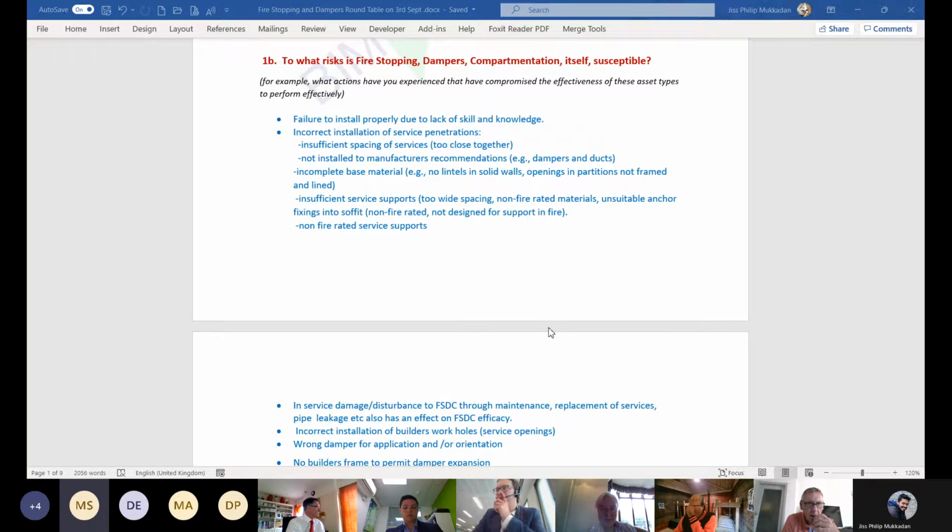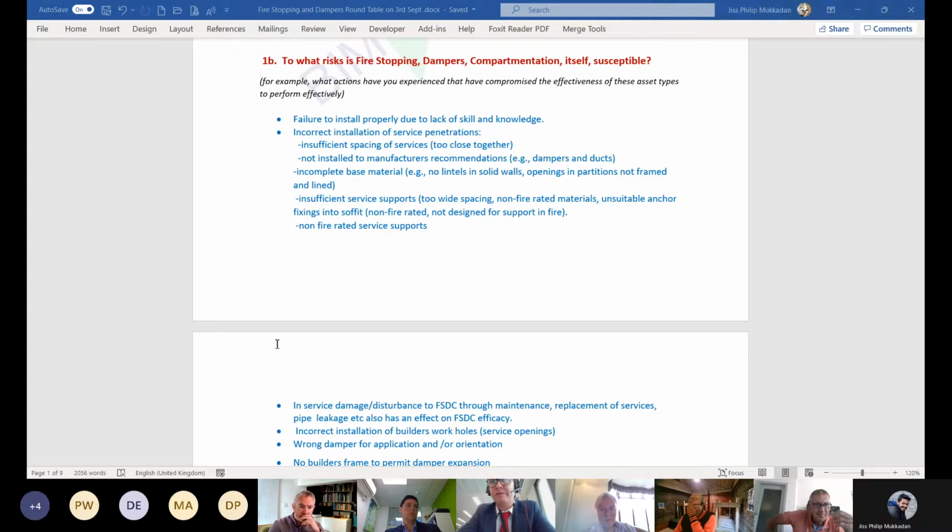I'm not trying to be too over the top. I had to look at 25mm holes for a long time as well. But honestly, the big thing here for me is, and you talk about Joe with the FIS as well, incorrect wall type and understanding the groupings of wall that's tested. BS476 walls versus 1364 Part 1 walls, direct compatibility with the test standards. And it's all about the incorrect vertical, and it should say horizontal seal. There are all different rules depending on what's been tested under what field. Just because you test something to Part 3, as Paul said earlier, it bears no resemblance to what you test under Part 2, and it's completely different to fire rated ductwork. They're just not the same thing.